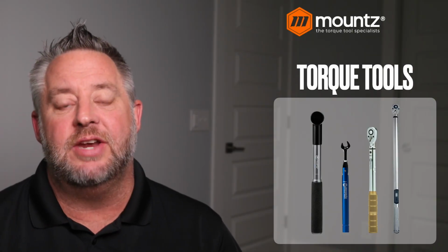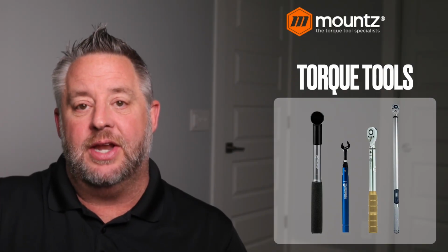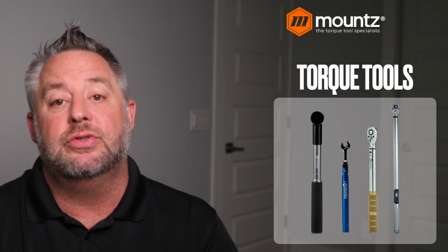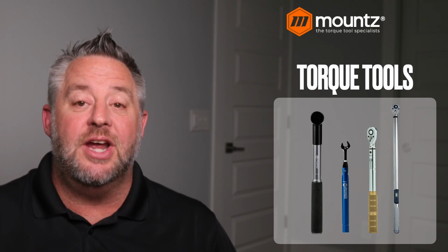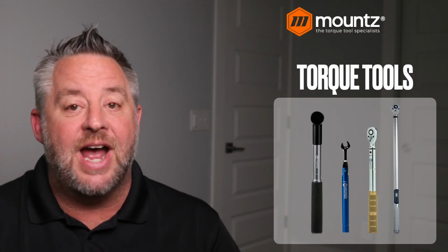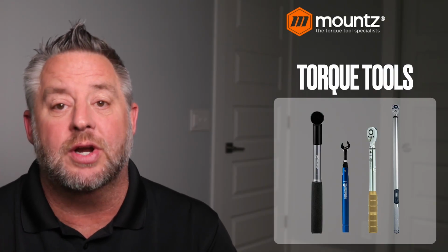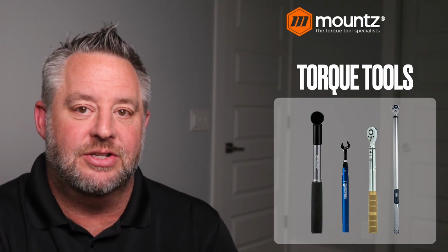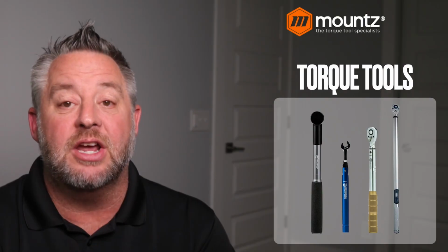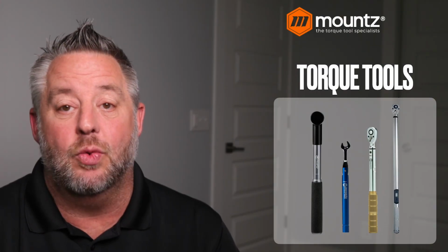So the click wrench is a very operator dependent type of tool. If the operator can pull that wrench slowly and evenly and wait for the click and then release it, those tools work fantastic. However, if you see an operator out on the line that will double click or sometimes triple click, going really fast, we're adding a tremendous amount of torque, sometimes 2 to 3 times the amount of torque that particular application is calling for. And so again, the click wrench is a very economical wrench. It's very easy to use, but it's very easy to misuse as well.